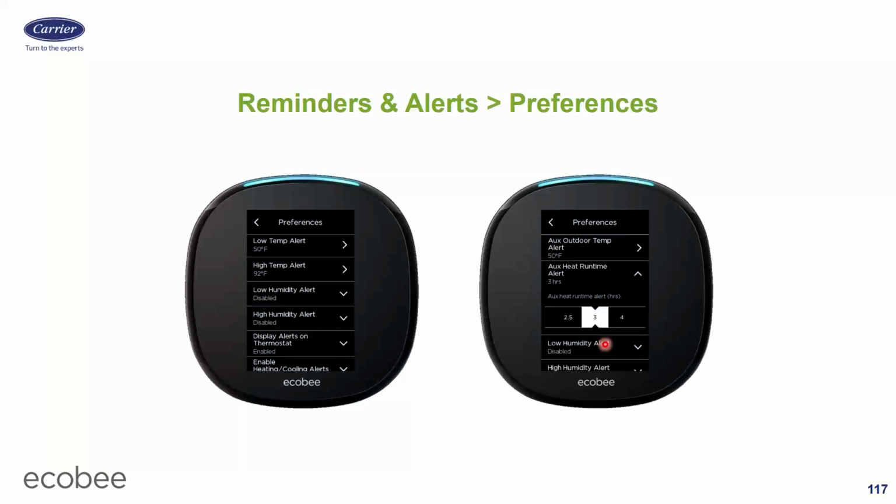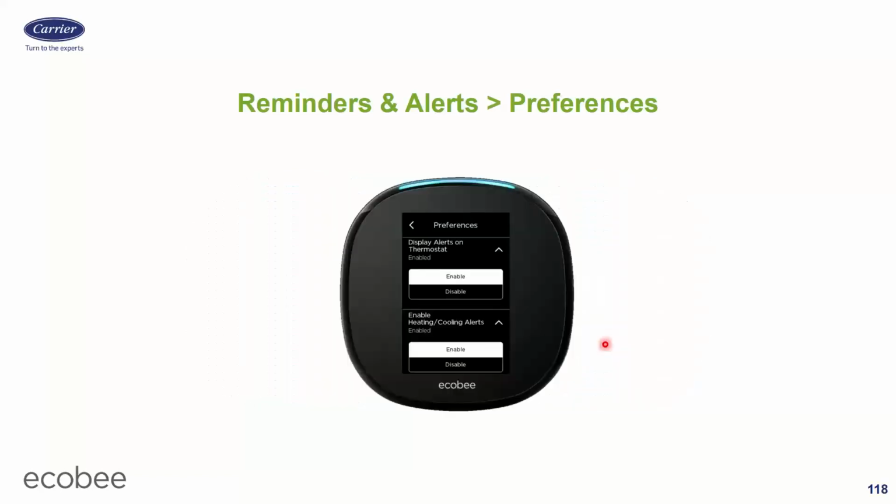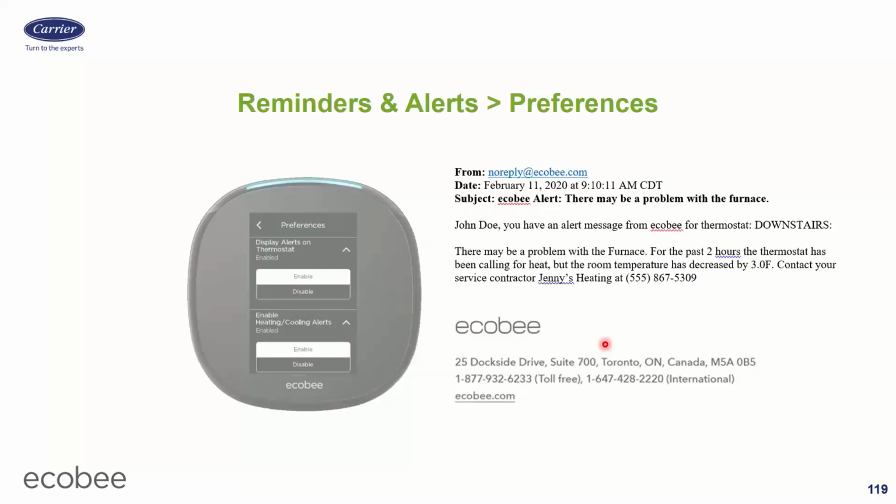Because when it's really cold outside, I want the heat pump to run and the electric auxiliary heat to run with it. So if the auxiliary heat's been calling for 3 hours, either the auxiliary heat's broke or the compressor heat's broke. One of the two is not getting it done, right? Or it's freakish polar vortex day, and I'm the one person who didn't have an oversized heating system, right? How many times can I mention oversizing in a 1 hour-and-a-half webinar when it's not even about that? Okay. Oh, we already talked about those two, so we're good.